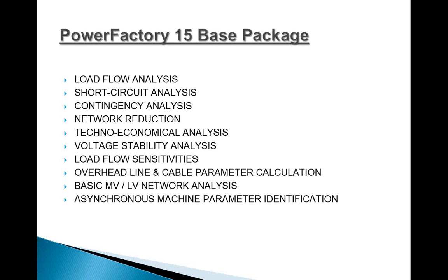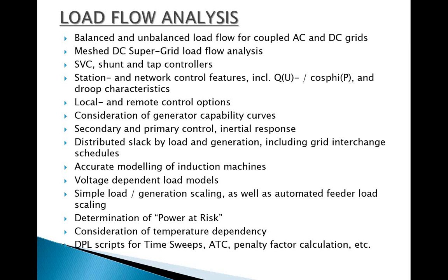So now we will see the detailed analysis functions which we can do in this DIgSILENT PowerFactory software. In load flow analysis, we can analyze balanced and unbalanced load flow for coupled AC or DC grids, meshed DC super grids. SVC, shunt and tap controllers are present. Station and network controlling features, different input modes like cos phi, V and Q, and group characteristics can be conducted. Local and remote controlling options are present in the software.